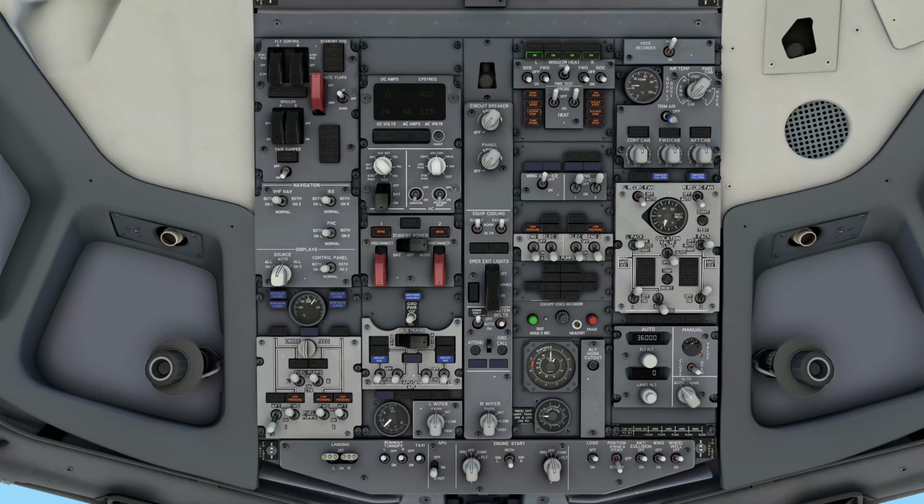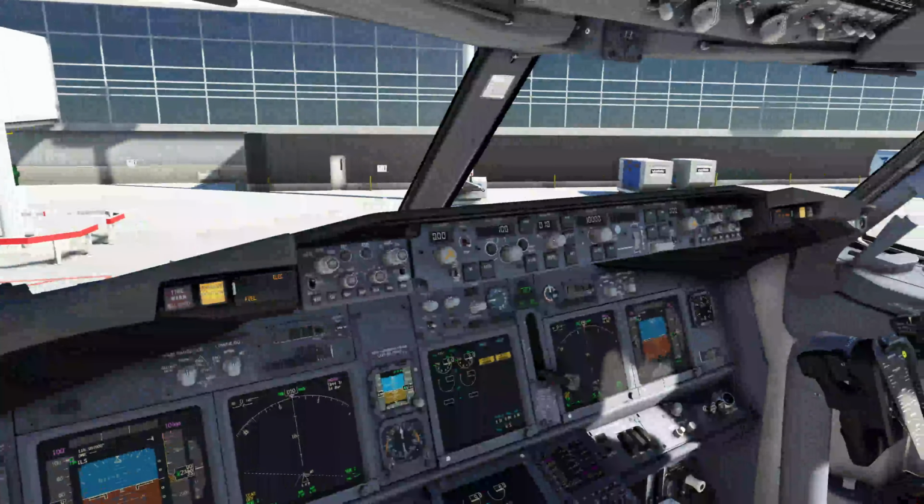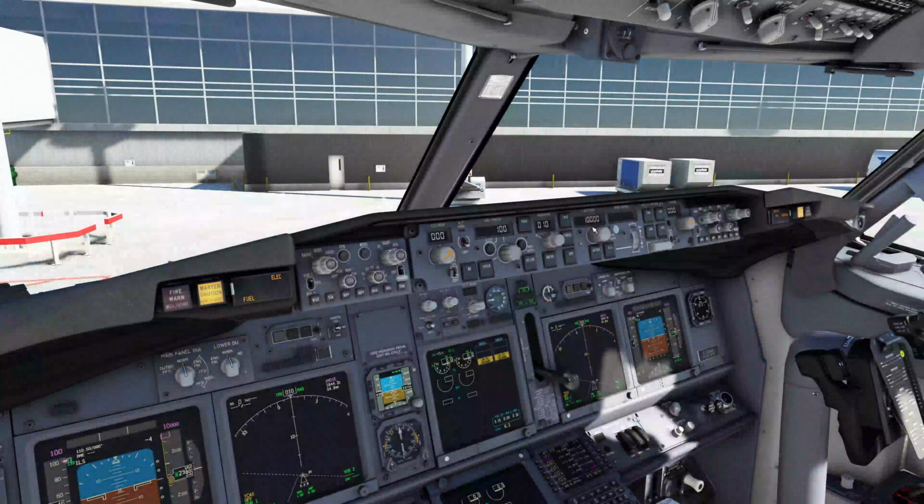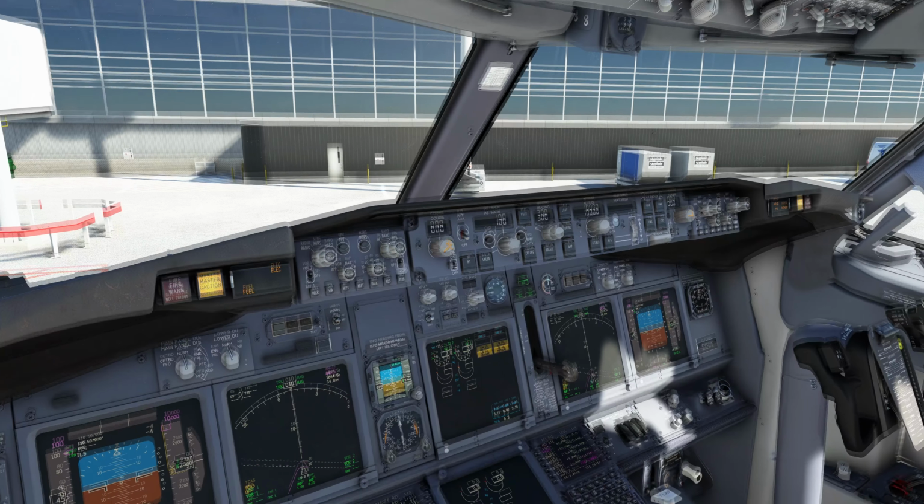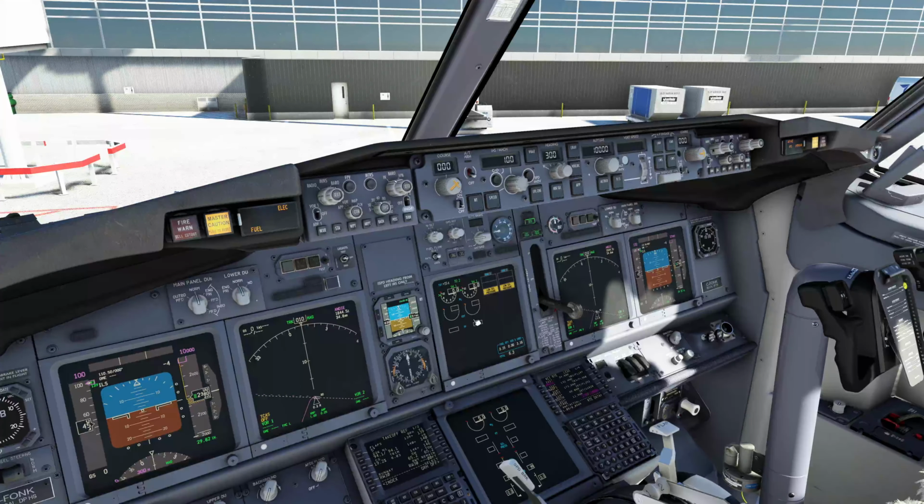MCP, all right. Let's get the MCP set up. So our initial climb is going to be 10,000 feet. Runway heading is 300 degrees. Since we're not going off to a STAR, we're going to be basically following heading mode for the initial takeoff. We'll set that up there. And our climb out speed is going to be V2 plus 20. So it's 146. We're going to set that to 166 as our initial climb out. It will go over to VNAV pretty soon after takeoff. That is all good.